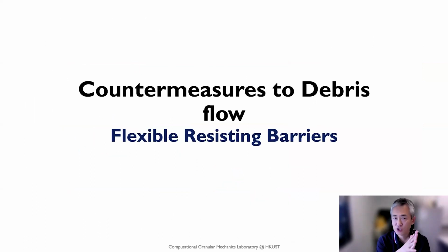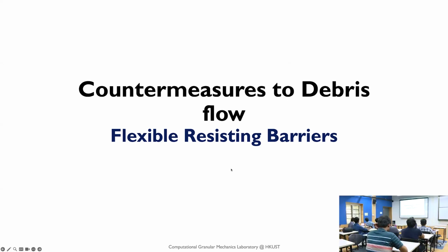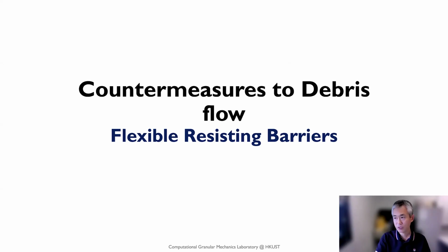So the key part I want to show today is that we can simulate debris flow, of course, and we can really choose different debris flow types. And the key part for engineers is how we can really develop countermeasures to mitigate the impact of the debris flow. In the past, people normally built the so-called check dam, a reinforced concrete dam or a concrete dam, to shut down this channel and use that to intercept part of the debris flow and reduce its impact.